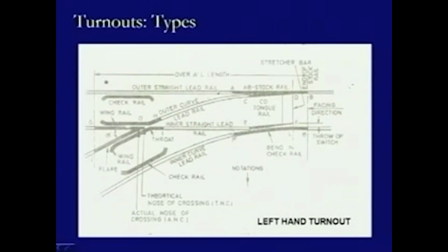So, on this direct side we have a combination of a pair of stock rails and a pair of tongue rails, and these two tongue rails, which are provided on either side of the rail sections like this one, are connected with each other. These are the bars by which they are connected, and these bars are known as stretcher bars. Okay. So, this is what is being shown this way, and then there is some distance at which this tongue rail will remain.